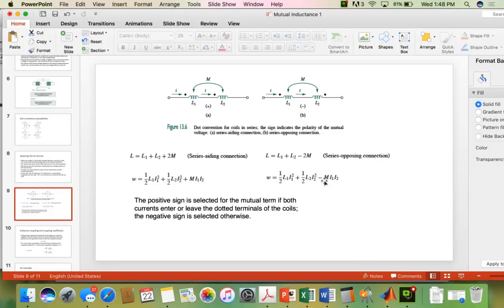And also, those voltage transmission lines are very high voltage as a general rule. So you've got issues with winding an inductor so that you don't get breakdown among the coils. So really, those inductive kind of filters are not built for that purpose. The other thing is, remember that you have to share flux.